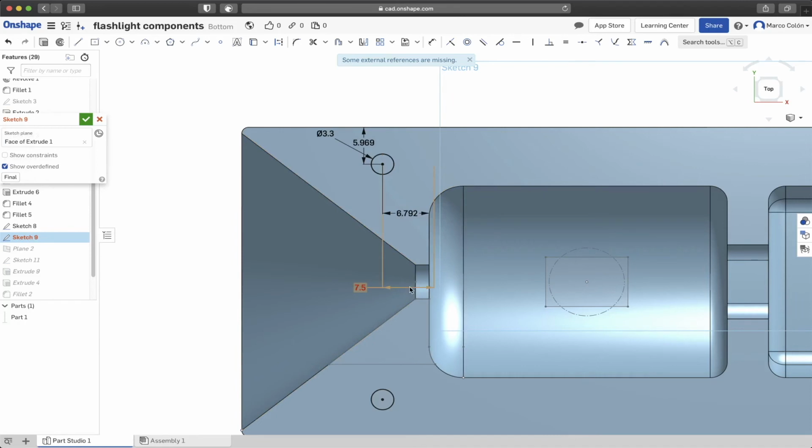Same thing here. It's looking for an edge that was present right here on this line. And I'm just going to delete that also. Delete sketch entity. And I added these two dimensions just to make it fixed in place. And that should be fine.